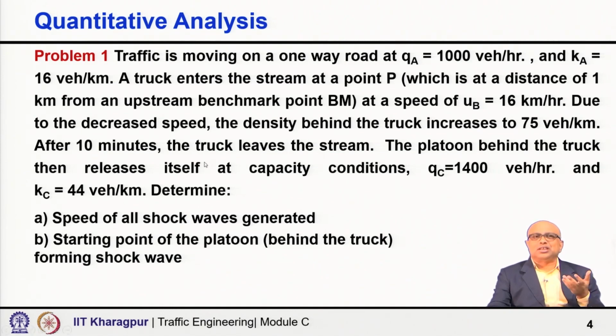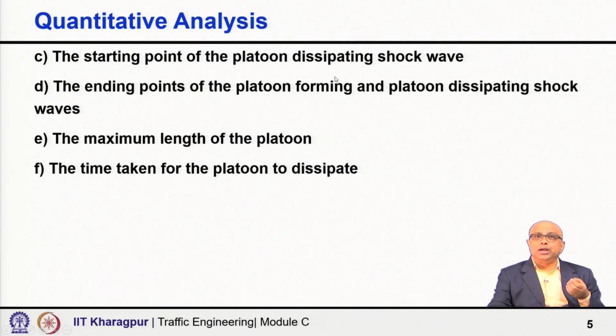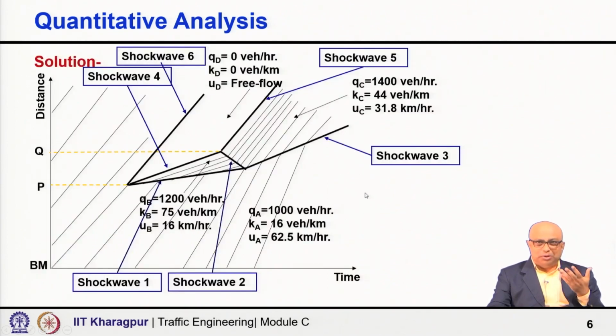Now, with all this data, what would we like to do? We would like to calculate the speed of all shock waves which are expected to be generated. Then the starting point of the platoon behind the truck, where the shock wave is formed. Then the starting point of the platoon dissipating shock wave, the ending points of the platoon forming and platoon dissipating shock waves, the maximum length of the platoon, and the time taken for the platoon to dissipate. Let us go one by one.